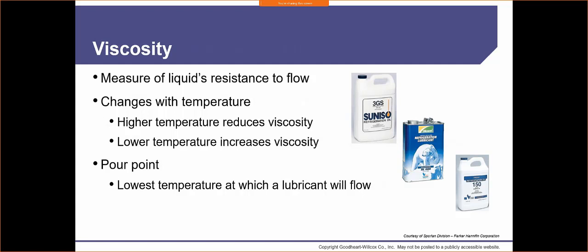And of course, viscosity. The most important part, I think, in my opinion: a measure of a liquid's resistance to flow. So we're going to have different viscosities based on different applications, just like our cars require different viscosities based on the different conditions we're driving in. There are two viscosities in car oil. Let's just say, for example, a 0W30. The 0 is going to take care of colder conditions, whereas the 30 is going to take care of the higher temperatures and conditions outside.